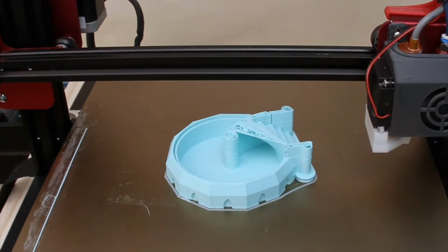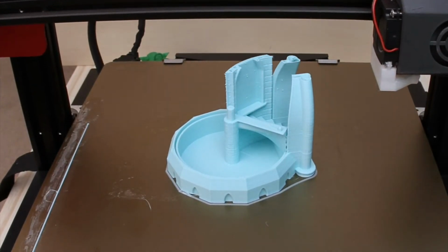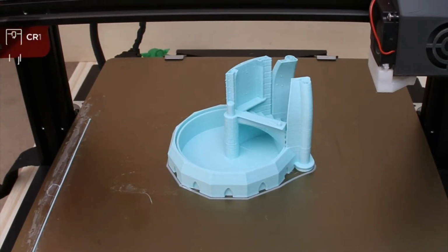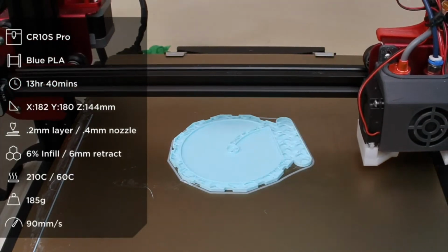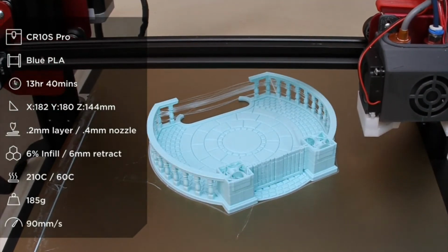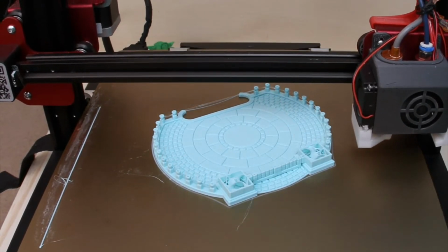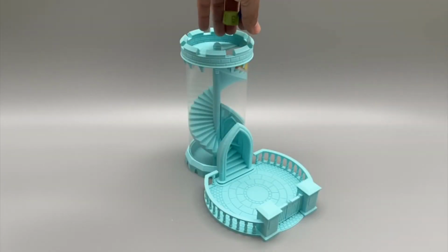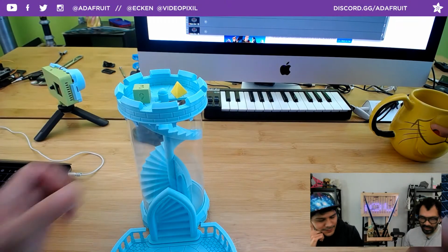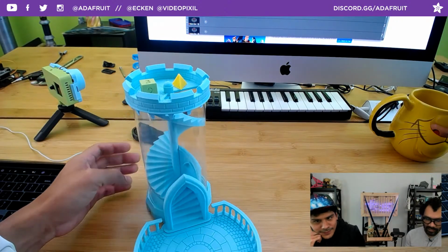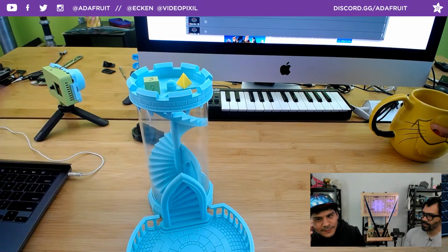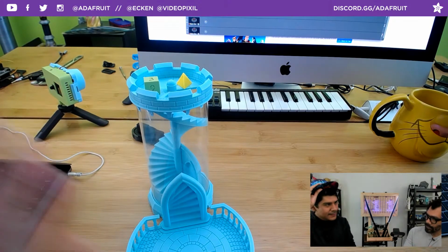And what impressed me was, first of all, the staircase printing. Tip on printing the staircase: if you're trying to time lapse it, it'll probably fall over, even with the Z-hop on it. So I had to turn off the time lapse for that, but we were able to get a very nice fail. And what I'm using for the clear part is the transparent sheets that are used for like overheads, binders, that sort of stuff.